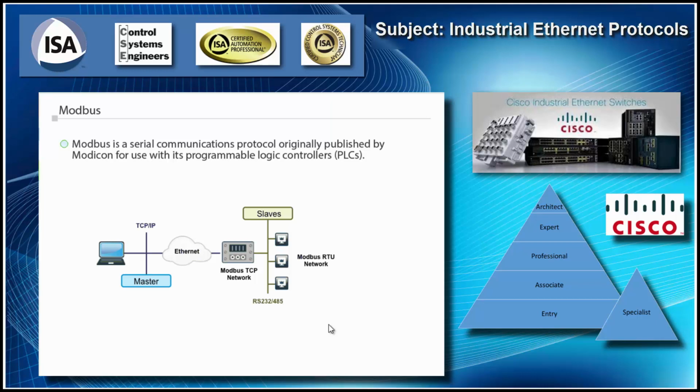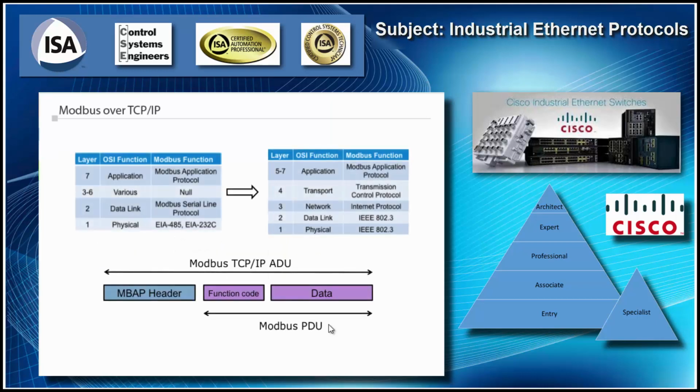In this figure, the Modbus TCP master can either wait for each response to return before the next request is issued, or it can send several requests at once in order to allow for parallel processing in the slave devices. In the latter case, the overall performance is improved. The Modbus protocol is still in use in the automation world because Modbus can connect IP Ethernet networks. The main change in the modern network is that Modbus now uses TCP/IP as a transmitting protocol.